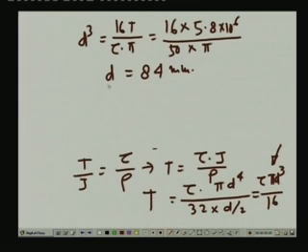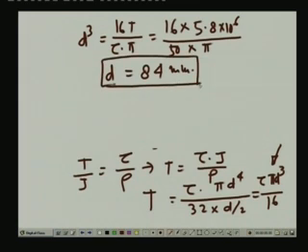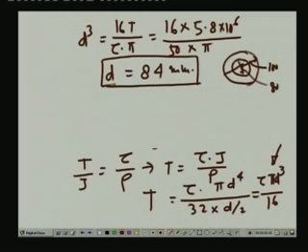Now, you see, this is the diameter which we are getting for a solid shaft or solid bar against a tubular one, which is having outer diameter as 100 and inner diameter as 80. So, outer diameter as 100 and inner diameter as 80, and as opposed to that, we have a solid section which is of 84 millimeter diameter.